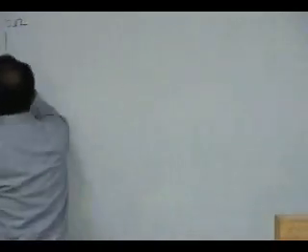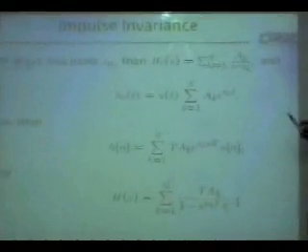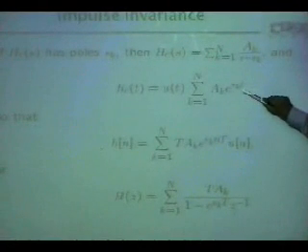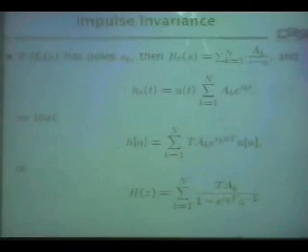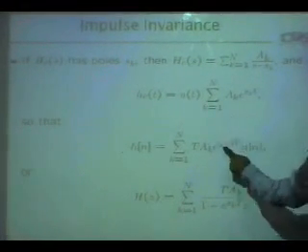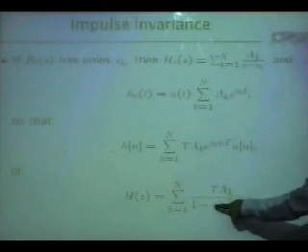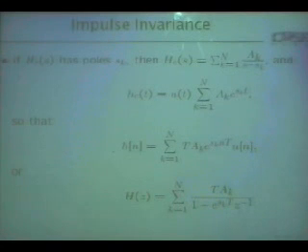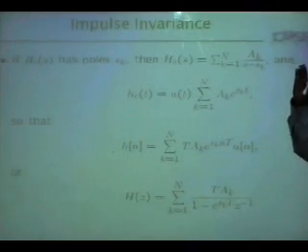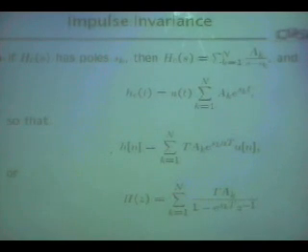Guaranteed, a stable pole in the S domain will be transformed into a pole inside the unit circle in the Z domain. As you can see, there are multiple of these s_k. You discretize them into a_k exponential, replace t by nT, u(n). You take its Z transform, then you have all these poles, exponential s_k T. Every pole s_k will be a pole exponential s_k T in the Z domain. So this is the relationship.